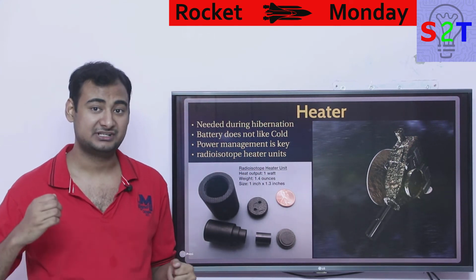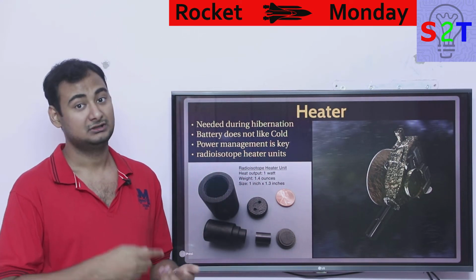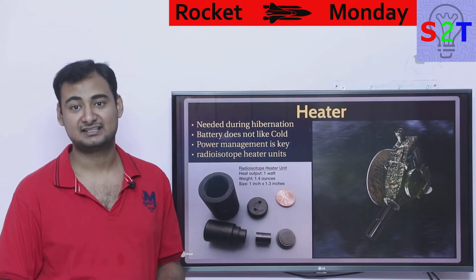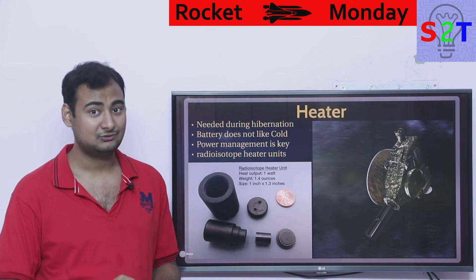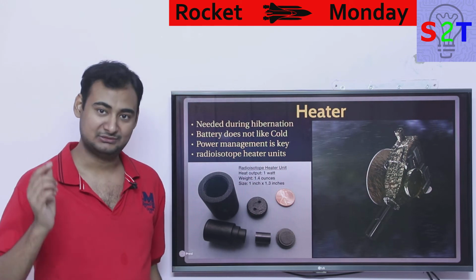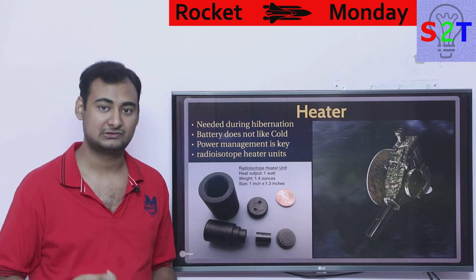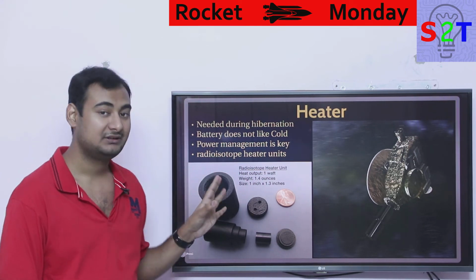It's not something where you can just say, okay, we're gonna make sure it's always hot, because then it's gonna stop working, or we're gonna make sure it's cold. Now the processor will like the cold temperature, the camera sensor will like the cold temperature, most things will like cold temperature. Heck, we use liquid nitrogen for overclocking. But the moment it touches the battery, it's like, no, I'm dead. And thermal sensors also need a reference point. So that is why we have heaters.